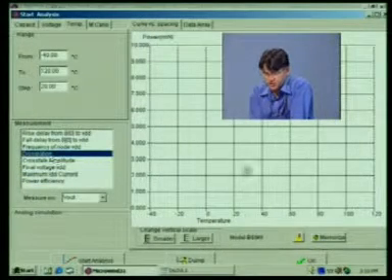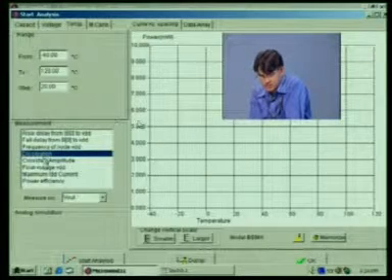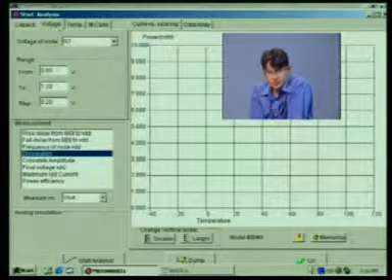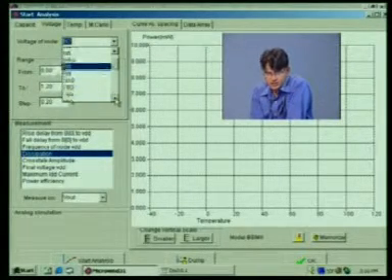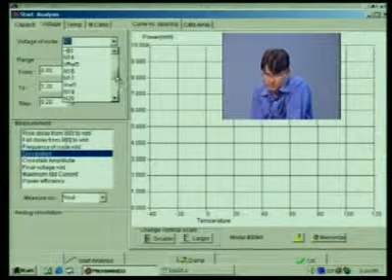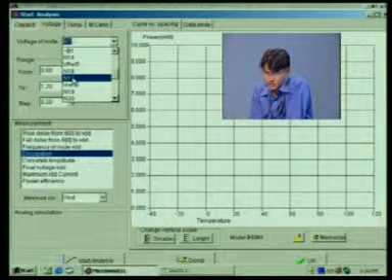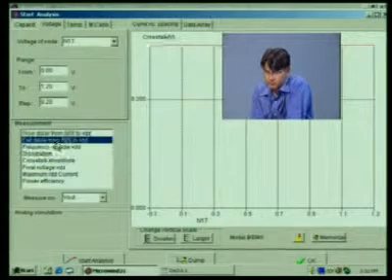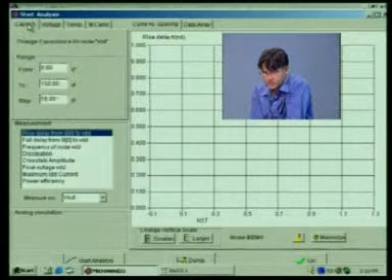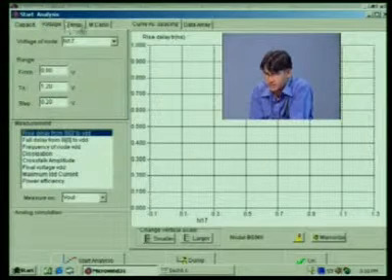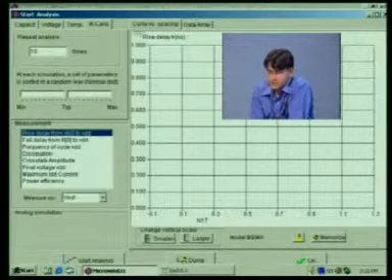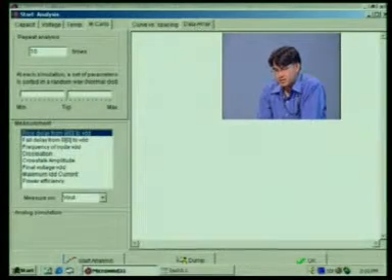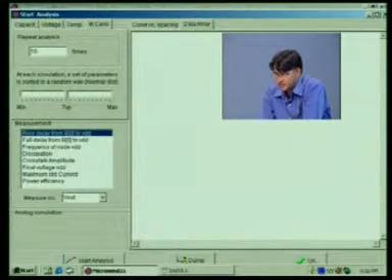You just analyze, suppose you want to know the dissipation of this circuit, just this and start analysis. So, it will give that kind of characteristic curves. Voltage, just select the node voltage where you want that power dissipation. Suppose I want it at this node, just select that, give the step size, give the voltage variation, select whatever you want and just analyze. So, this kind of parasitic capacitance analysis, voltage analysis, temperature analysis, Monte Carlo analysis, you can do with the help of this. Okay. And after analysis it will give that data array.